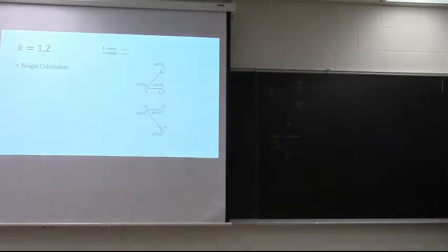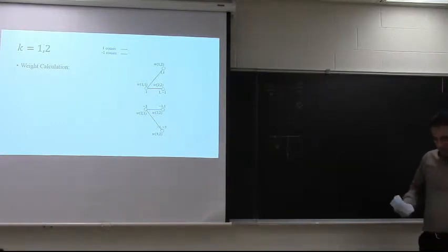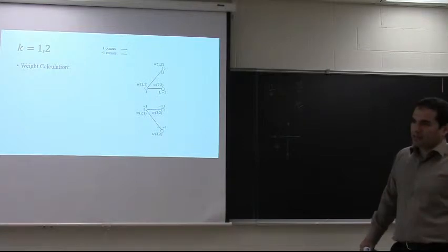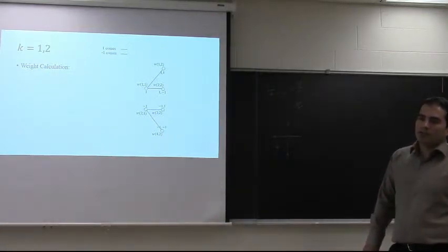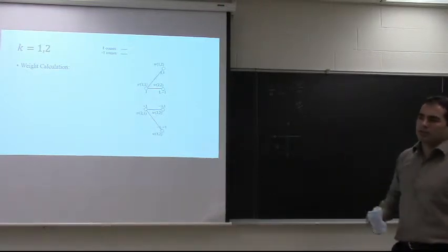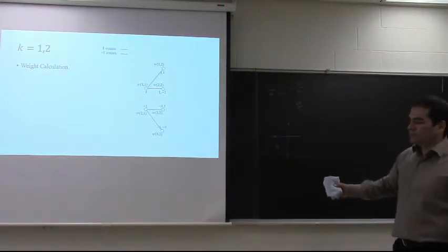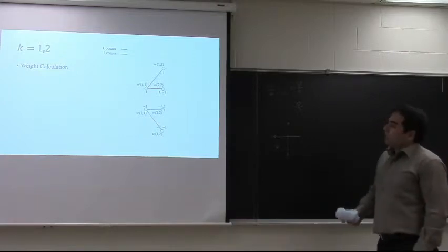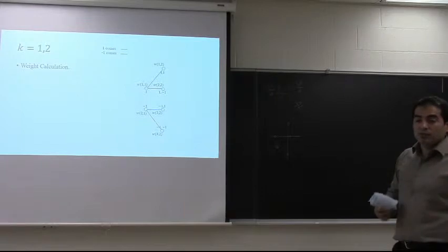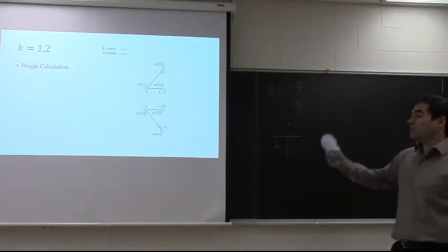Let me just explain something to you before. This is not the only way that you can implement the trellis diagram or implement the Viterbi algorithm for the CPM signaling or whatever. Maybe you can go for a lower number of states, but in that case you need to do much more complicated programming. This is the simplest way.